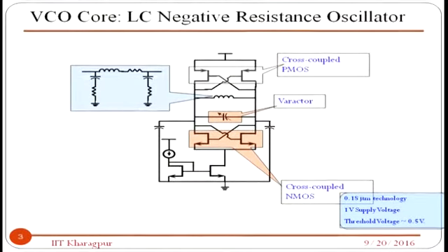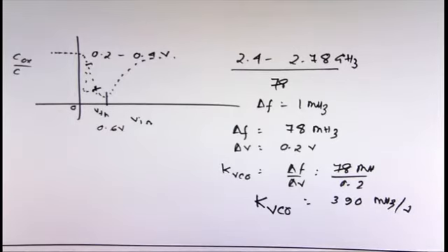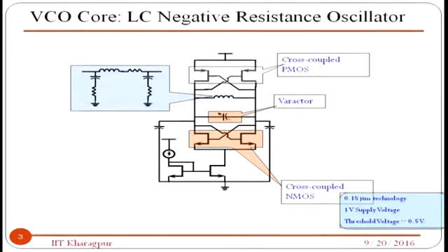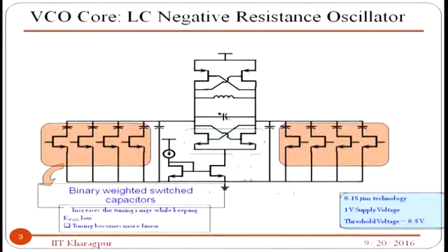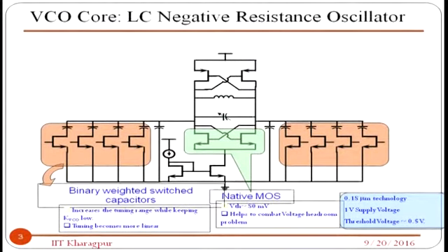That is the first thing. How do you do that? To do that, the only option is to use this earlier design called band select filters. So what is this? You have your cross-coupled system, then you can have several such. Instead of this single MOS varactor, you can have multiple banks of capacitors, and those capacitors will be connected with a switch.